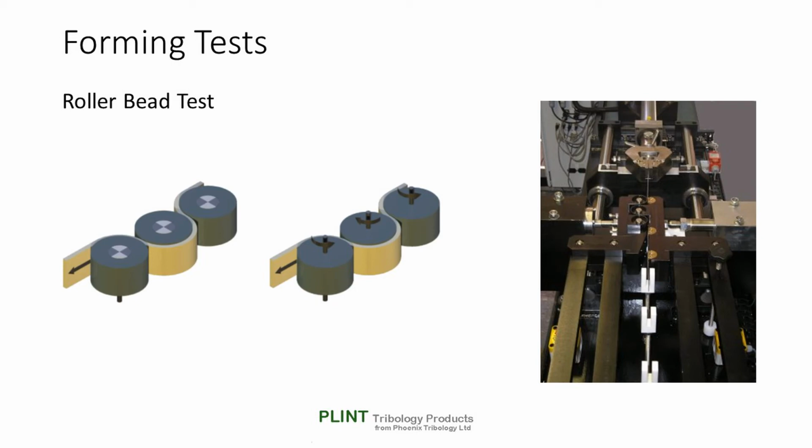For each sample test, it is necessary to establish the initial clamping force needed to close the tool. The closed position for the tool is initially set by mechanical stops. The procedure for establishing the required clamping force is to load a sample and progressively increase the load while monitoring closure of the tool. The load at which the tool first closes against the stops is then taken as the clamping load set point for subsequent tests.